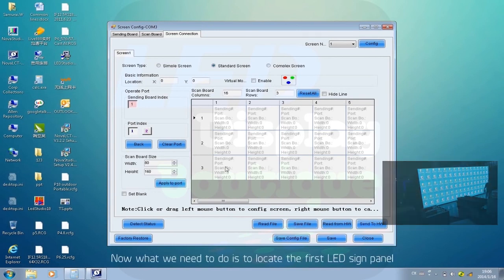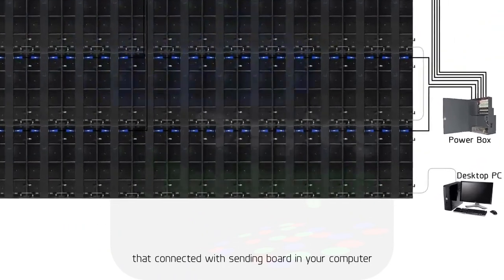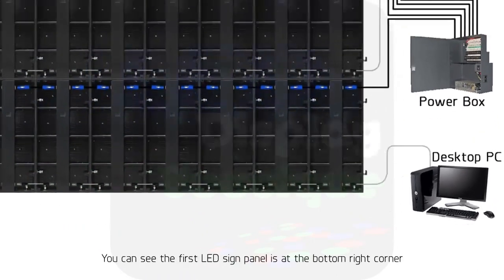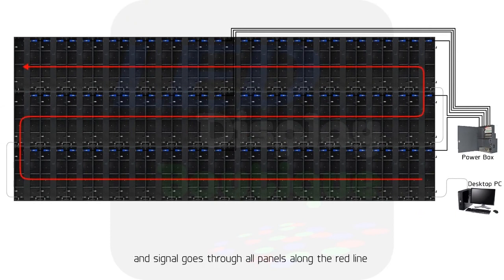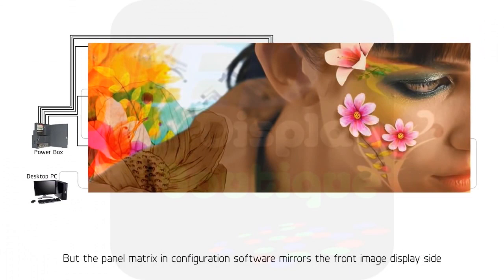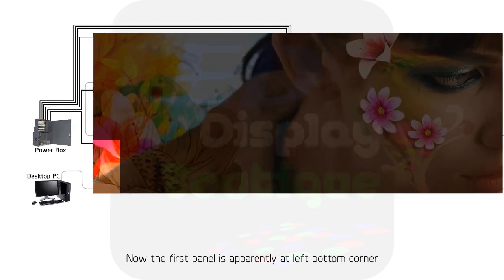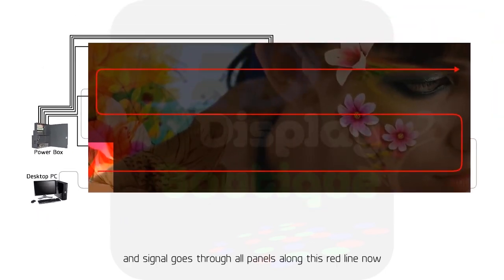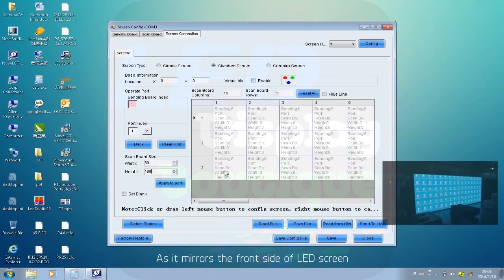Now what we need to do is to locate first the LED sign panel that is connected with the setting board in your computer. You can see the first LED sign panel is at the bottom right corner, and the signal goes through all panels along the red line, but the panel matrix in the configuration software mirrors the front image display side. Now the first panel is apparently at the left bottom corner, and the signal goes through all panels along this red line now. We go back to screen connection.